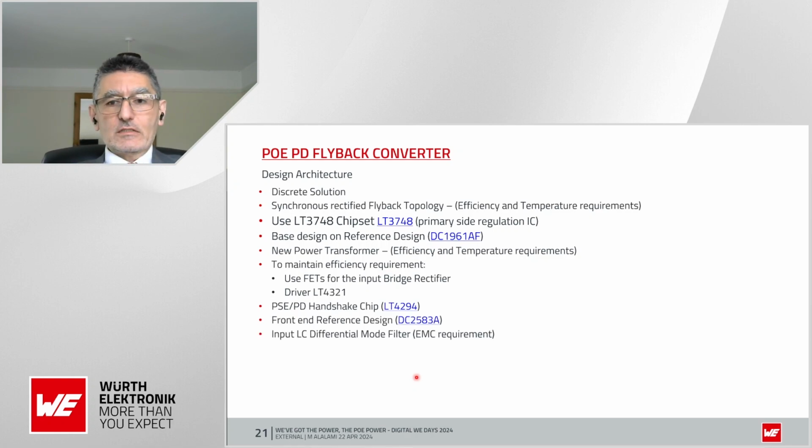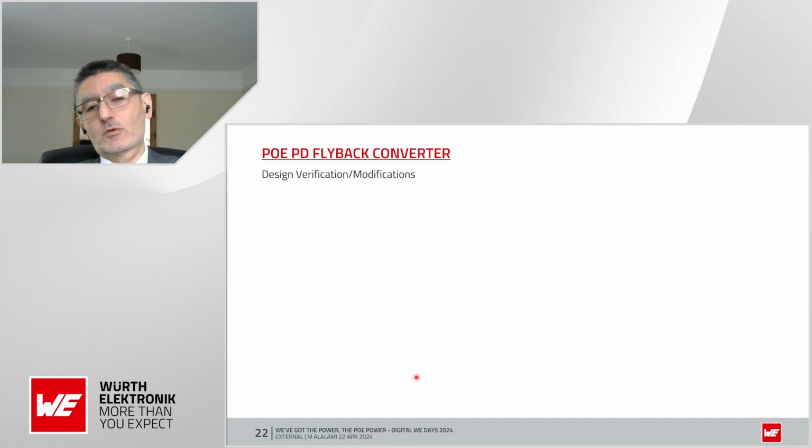Front end design was based on this DC2583 reference design with evaluation board. So we had basically the full system put together if we wanted to straight away in order to do some testing. With the addition, of course, of input filtering, common as well as differential, and of course output filtering to limit the ripple to the 5% requirement.